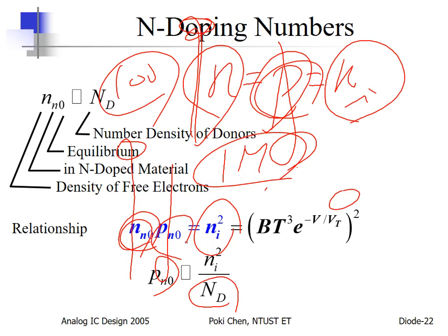Much less than 1%, much less than 0.01% of the electrons need to be recombined. So my total number is almost the same. I simply have too many. So again, the concentration of electrons will be almost the same as the doping concentration. That is n-type doping.